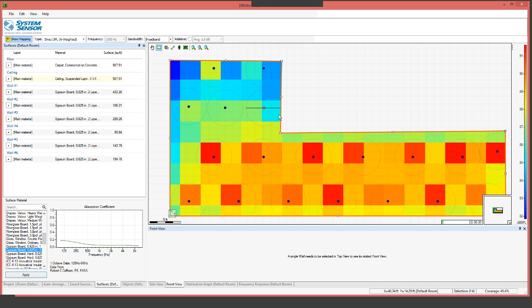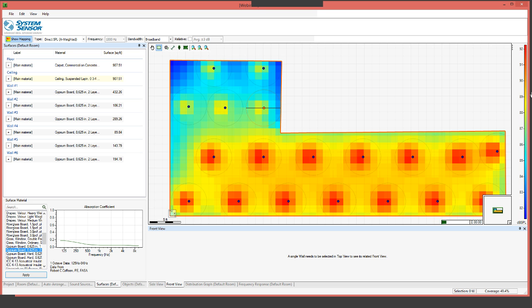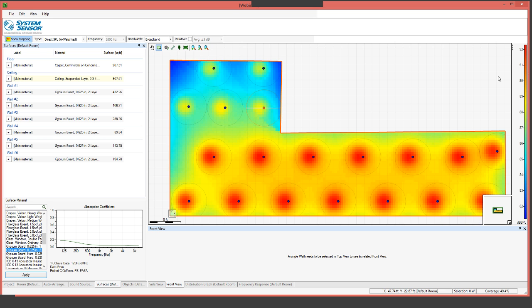If I'd like to have a specified SPL range, by default it automatically chooses the levels for the devices in the room, but I can also fix that by selecting the SPL list over here on the left, or on the right, sorry. So next, now that we see that the levels are in a useful range, let's take a look at what the STI is for this room.